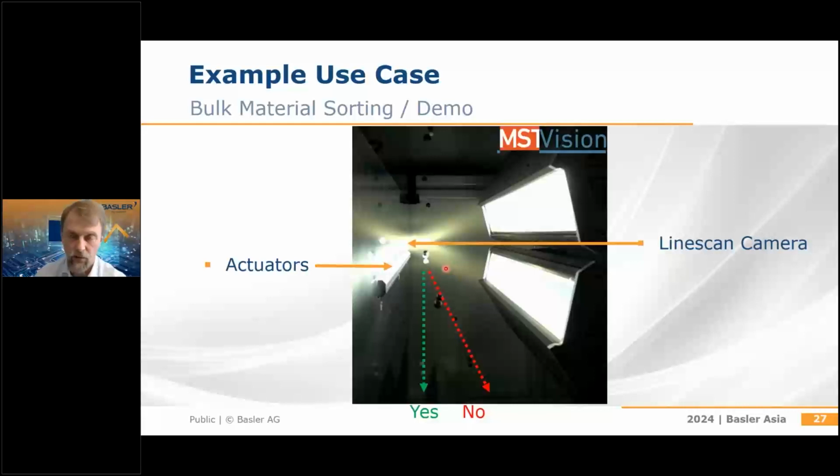So there's a closed loop control that is taking care of a correct welding process. The processing cycle of 60 microseconds, not milliseconds, it's only 60 microseconds, includes the exposure time, the transfer time, the decision-making time, and sending the result into the laser.